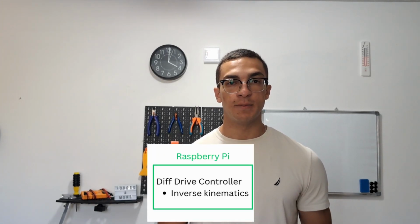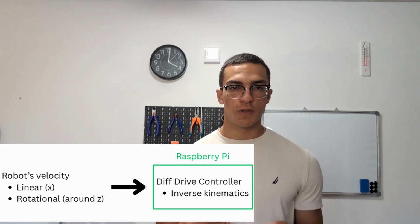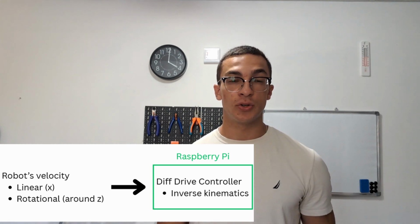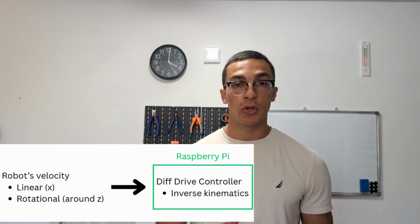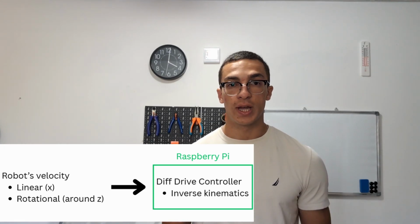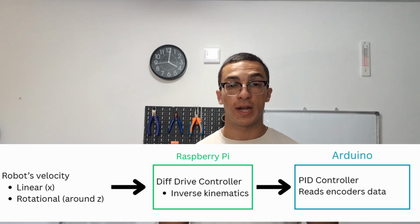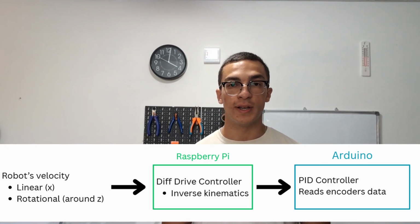The diff drive controller runs on the Raspberry Pi and takes as input the desired rotational and translational velocity of our robot, which is published at a specific topic. It then applies the inverse kinematics equations for a differential drive system to calculate the appropriate rotational velocity of each wheel based on some parameters that we set. Afterwards, those calculated velocities are sent to the Arduino via serial communication. Then, the Arduino implements a PID controller to calculate the control signal that will be sent to the motor driver in order to rotate the wheels appropriately.